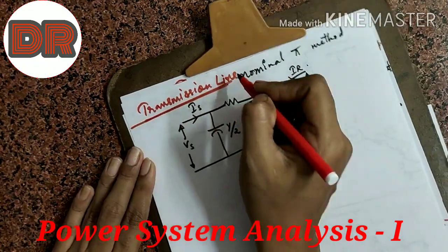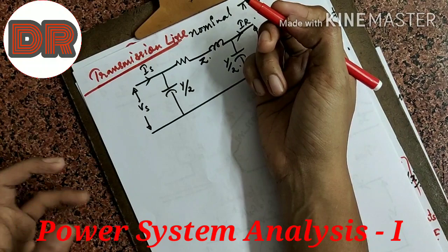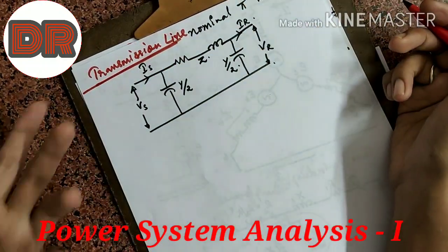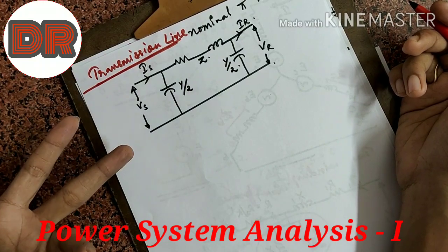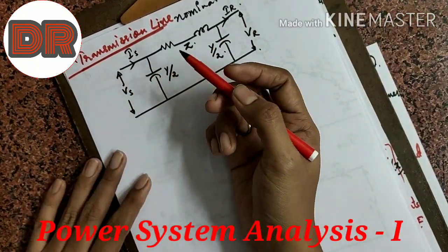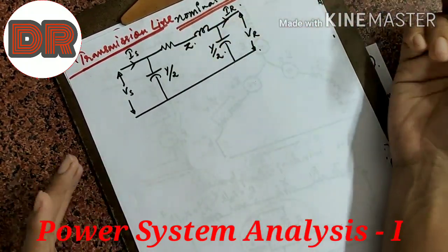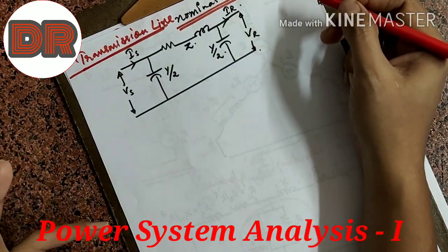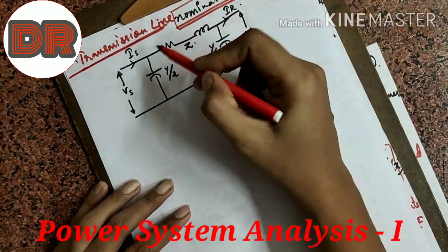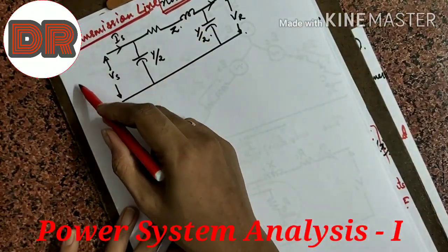All these are basic components. There may be some other components also, but they are not very useful for us to do the analysis for theoretical purposes. So we write only generators, motors, two winding transformers, and also the transmission line. For the transmission line, normally we can represent it with the nominal pi method. There are two methods, the nominal T method and the nominal pi method. Normally we use the nominal pi method for the representation when we do the analysis of power systems. This is how we write it.